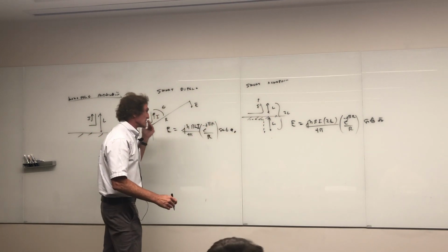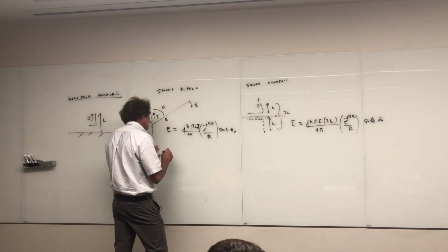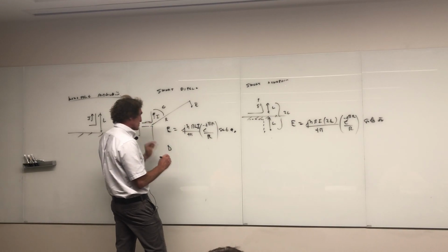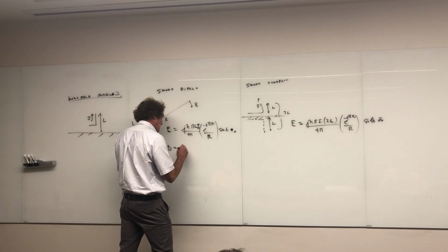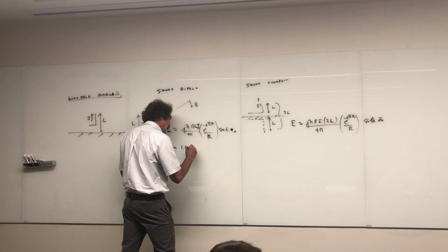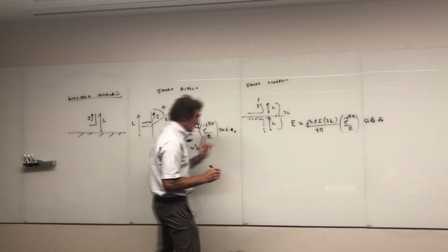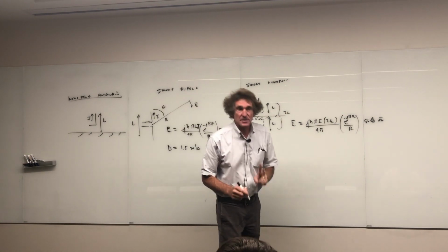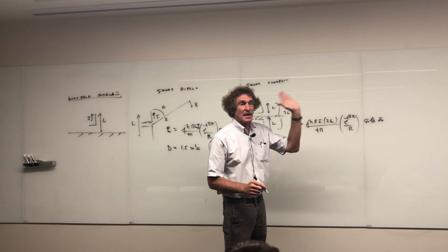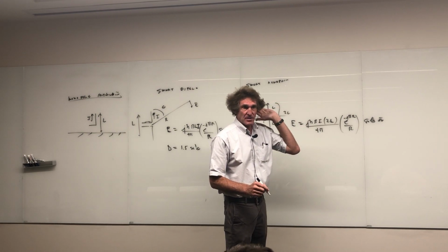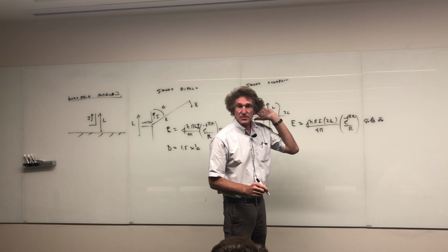They're identical otherwise. When you come here, the directivity for a short dipole would be 1.5 times the sine squared of the angle theta. The directivity for this doubles, and here's why. The power is only radiated in half the region. Everything below the horizon, there's no power radiated.